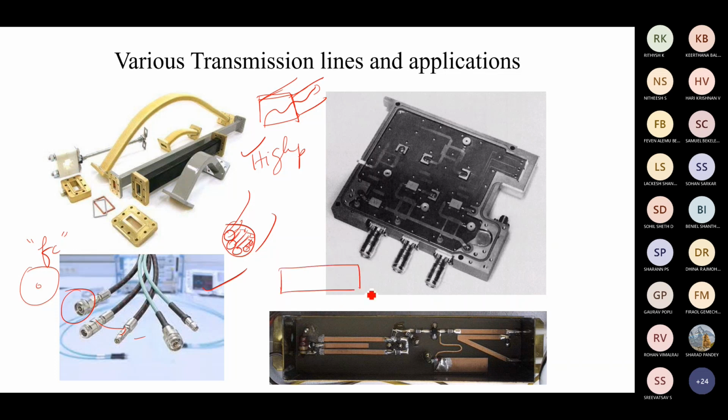So we will take a substrate. This substrate will be nothing but some polymer material, having its own dielectric constant. By placing two wires, that means thin films, top and bottom, we can control the electric field and magnetic field, everything. And by that we can construct some structures. So when you take the cross section, you will see this type of structure. And this is the top view. When you see this top view, this is the transmission line.